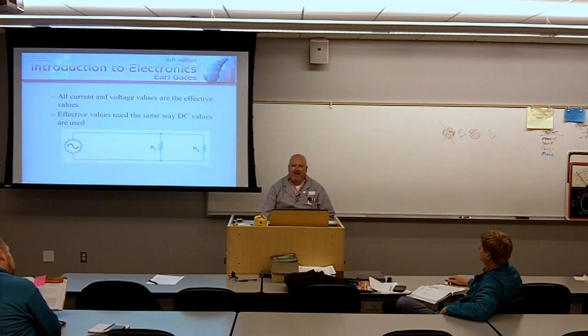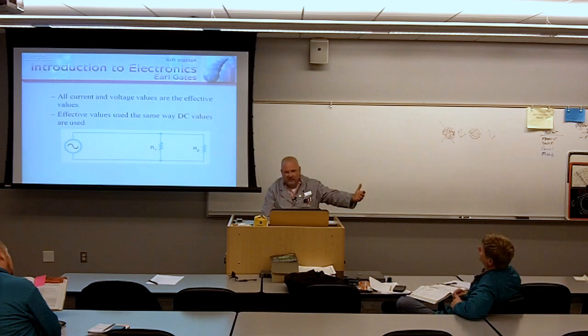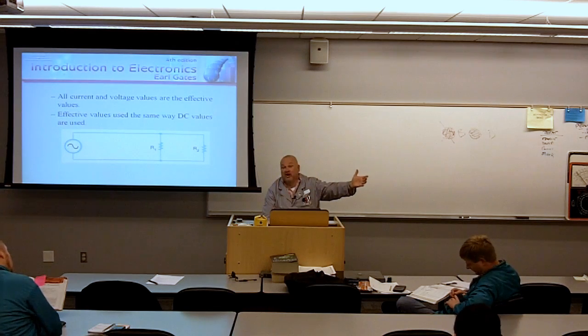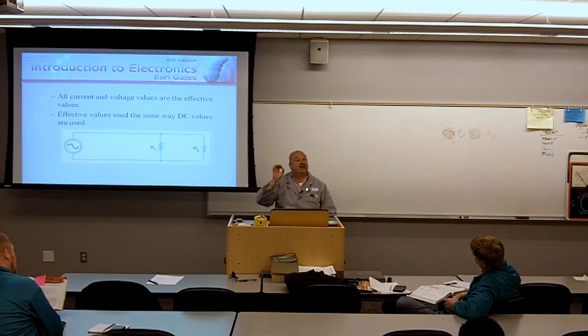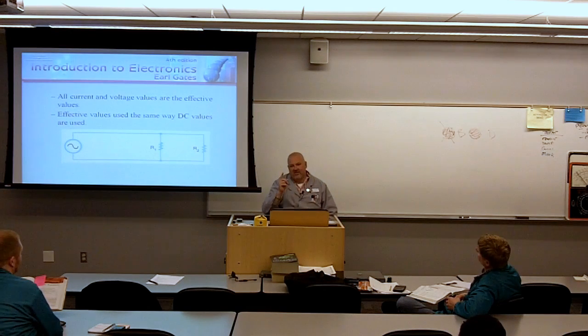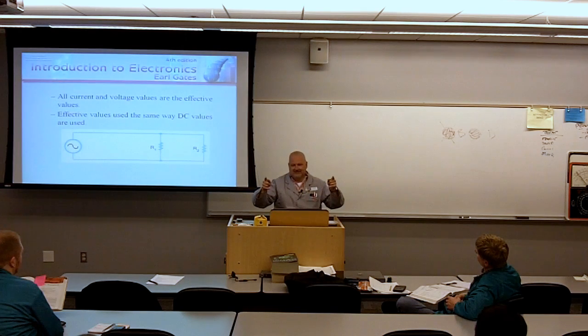So if I give you a lab that says you need to have a signal at 20 kilohertz and you need to measure 12 volts peak, do not get a DMM and try to measure it. If I tell you need 7.5 volts RMS, do not try to use a digital multimeter. Because above 1,000 hertz, the data just goes out to lunch. It's not designed to measure that repetition. It's designed to measure AC power. That is the number one reason we really use the oscilloscope. Because the oscilloscope, where you're looking at time versus amplitude, doesn't lie to us.